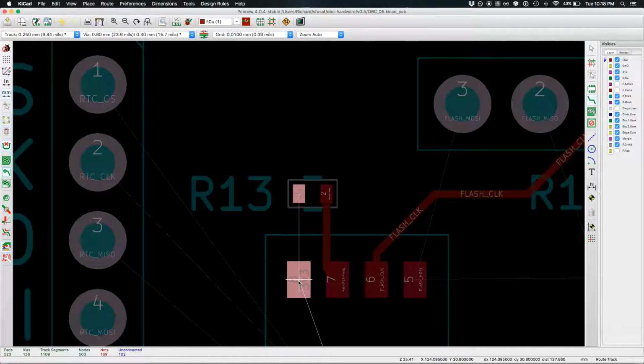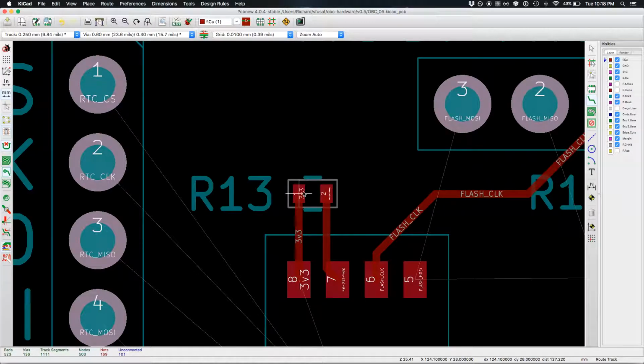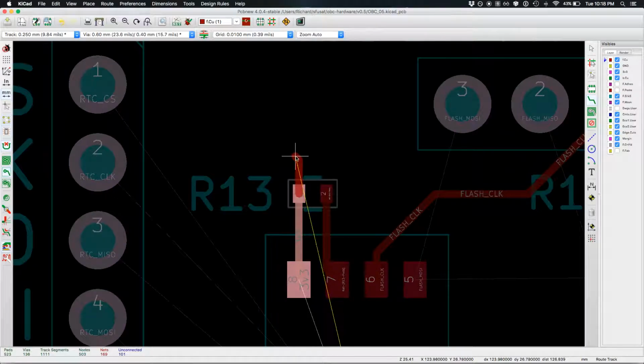So this pin is labeled 3v3, and so is this one. These two are close, so we can just connect them, that's fine. But then we don't need to route these 3.3s together with tracks because we have the plane layer on layer 3.